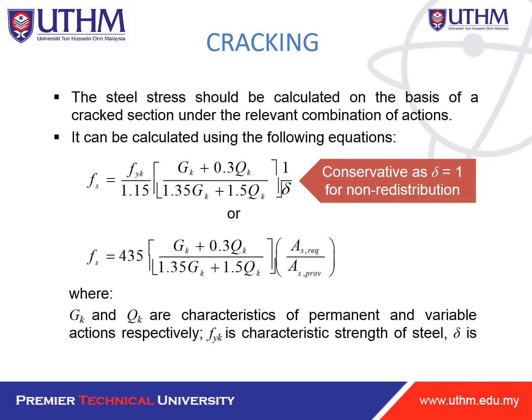Okay, so for the cracking, the steel stress should be calculated based on the cracked sections under the relevant combination sections. It can be calculated using the following equations. So conservatively, sigma equal to 1 for non-redistribution moments. So you're using these As equations, or either using this.